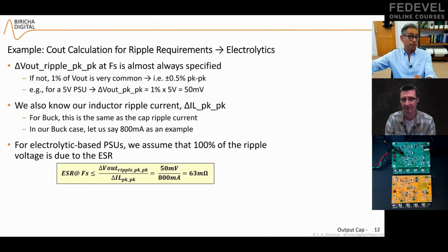And 150 microfarads was the one that I was going to buy to make sure that I don't violate the undershoot requirements. I would like to point out here, I'm sorry for interrupting, because I'm sure everyone who ever designed any switching power supply read somewhere about this ESR, keeping ESR low.